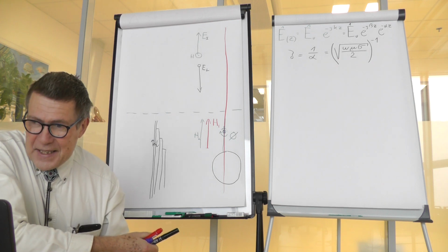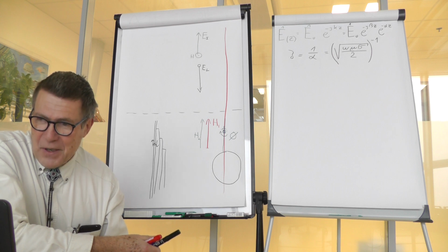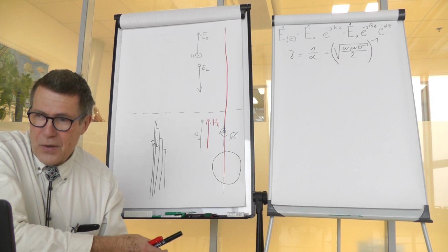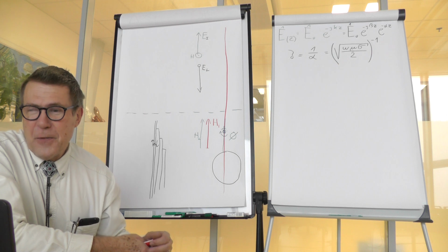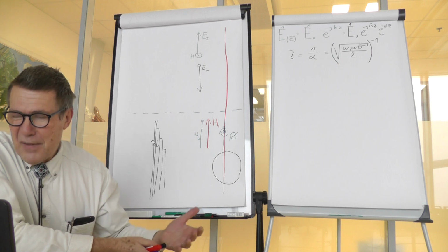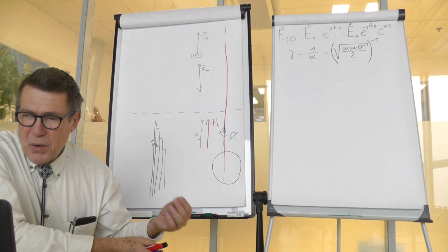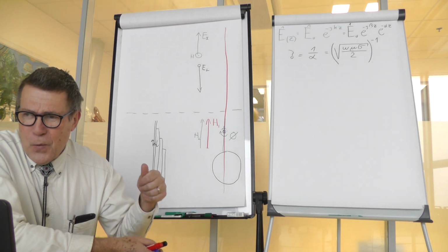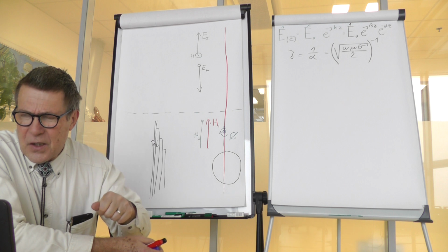I mean, with DC, you would have the same current density through the whole conductor. But even at 50 Hertz, there is something like 1 millimeter through which most of the current would flow, and you would not be able to get it inside a conductor.